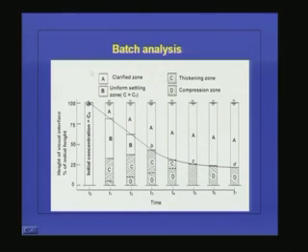So, the sludge we are taking here, and this is the time. What we have to do after that, with respect to time, is find out the position of this sludge. We will be observing different zones in the settling. This A portion is the clarified zone, and another zone will always maintain the same concentration as the sludge we introduced in the first column, and we will have a compression or thickening zone here, and the bottommost portion is the compression zone.